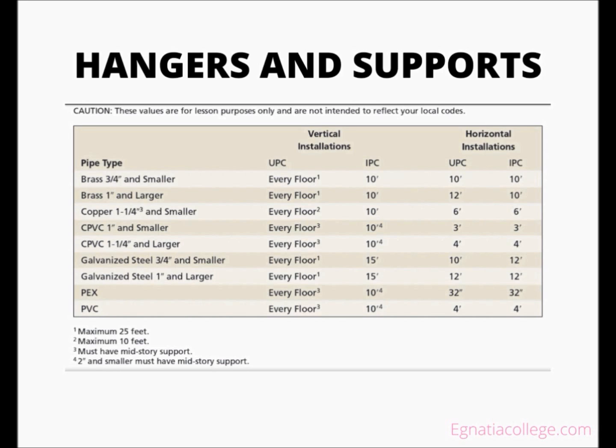A plumber often installs additional wood boards so that hangers and supports can be installed where desired or where dictated by codes. Maximum spacing between hangers and supports is also dictated by codes, and different materials have different spacing requirements. Pipe routes are often determined based on the most practical or productive method of installing the required number of supports. The location of piping can determine when support is needed.